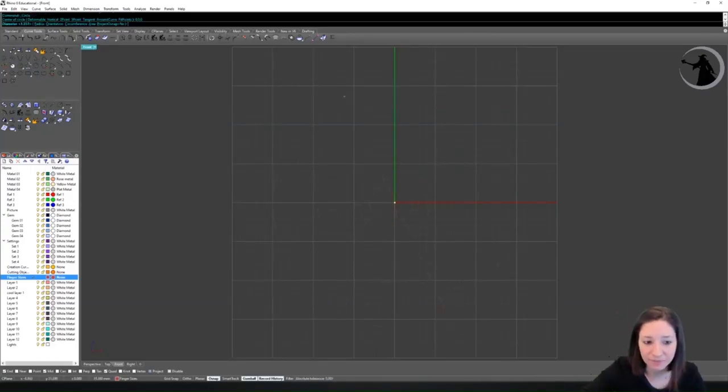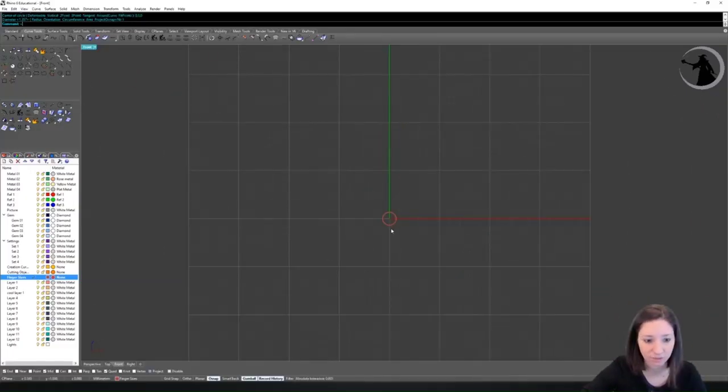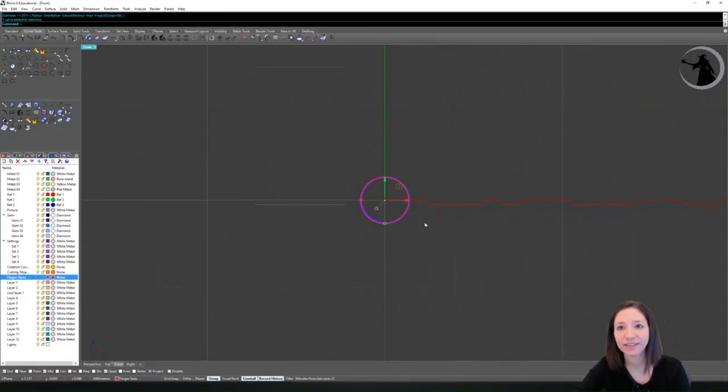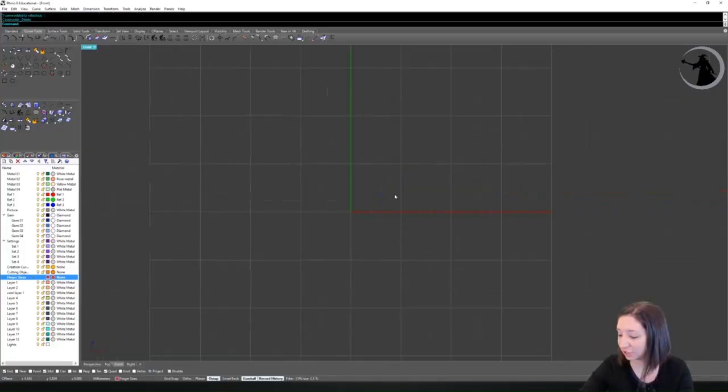And if we programmed it right, you should see that circle has snapped to the center of your construction plane. And again, highly recommend drawing your finger hole in the front view. Oops, I just hit enter. If you hit enter, then it will just draw you a random circle and then you have to delete it. If you right click your mouse after using a command, it will reactivate that last command that I did.